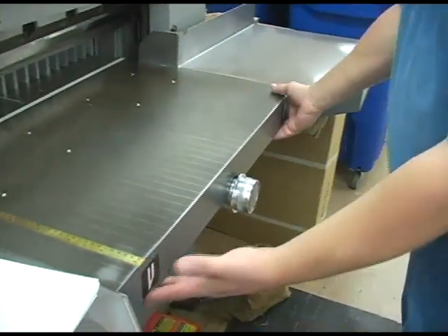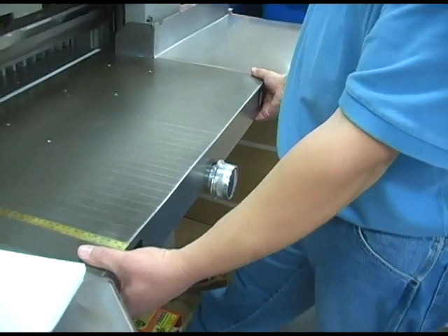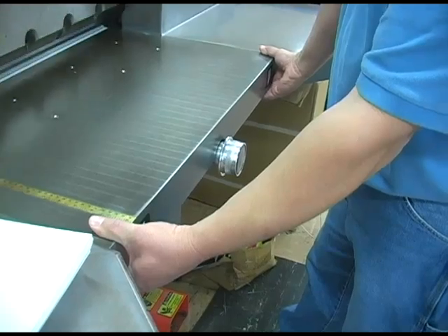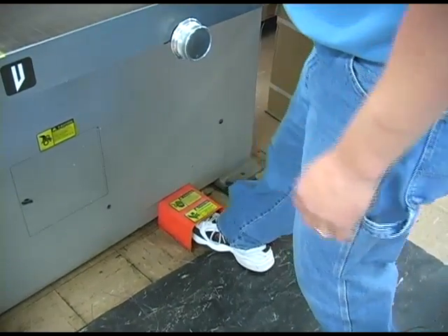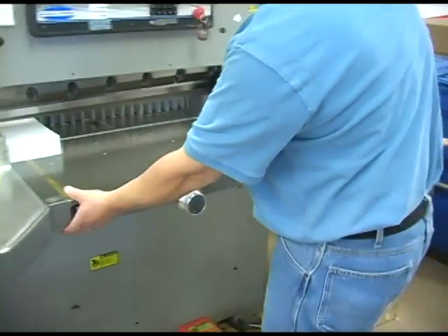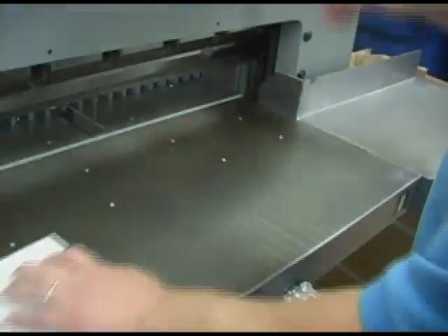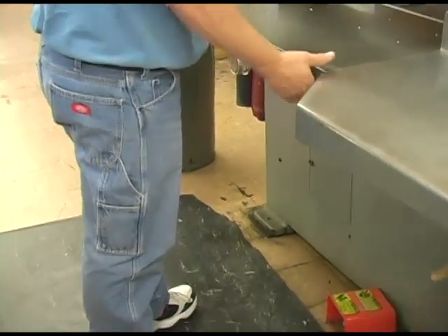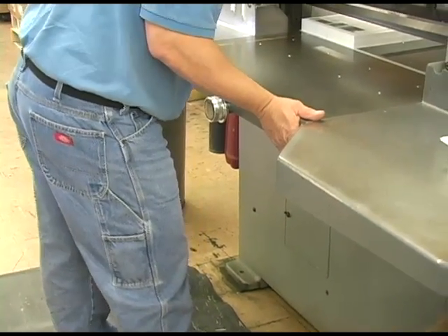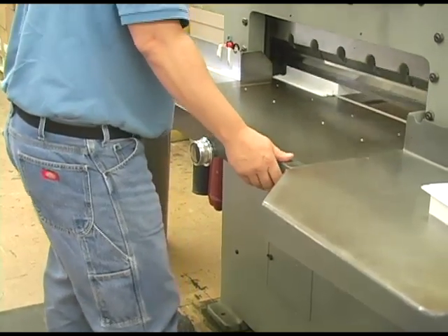The cutter has a system of interlocks to keep operators' hands out of the path of the moving blade. Specifically, the blade cannot be activated unless the operator depresses the foot pedal while simultaneously pressing two widely spaced hand-operated buttons. The interlock system is an engineering control because it is built into the machine to protect workers from a hazard that cannot be eliminated.